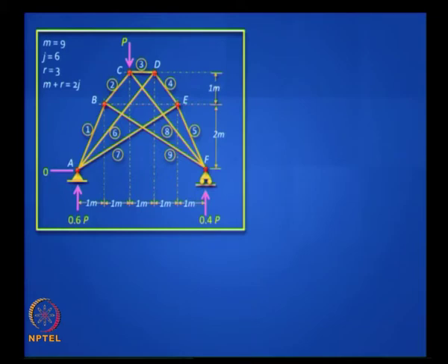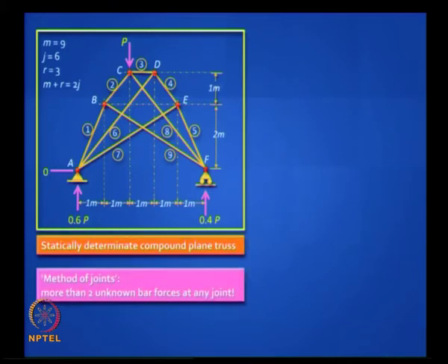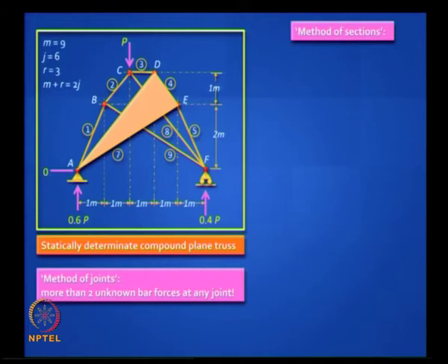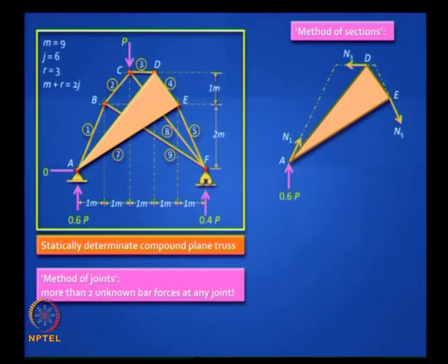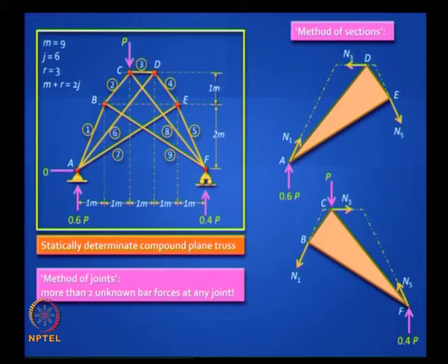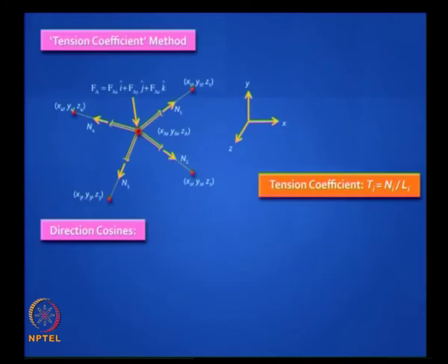This is again a compound truss but statically determinate. What you can do is view that segment as a triangle and separate out that triangle, which means using a pair of mental scissors and snipping through those connecting bars. You expose those bars, and here you have one look at this picture and you know that there are only 3 unknown forces. You have 3 equations of equilibrium available, you can solve for it. Or you could take the other triangle and you could solve for it, and once you've got the idea, it's easy to calculate because you can use any 3 equations and solve it.